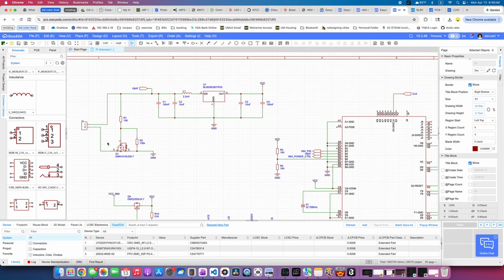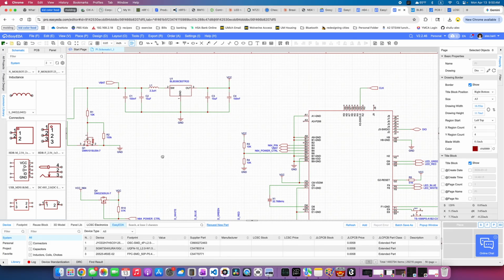If the battery was reversed, the gate to source voltage would be negative, so the MOSFET would be off. That would not let current go through from this header to ground. If we didn't have this MOSFET and we flipped the battery, we would have current going from ground through the circuits, through the battery, and it would likely damage our microcontroller and other circuits. So that's that.